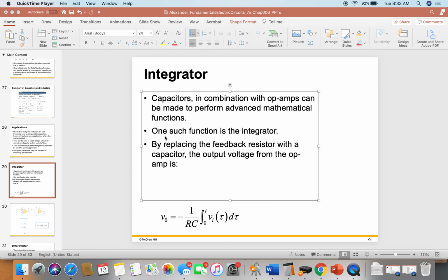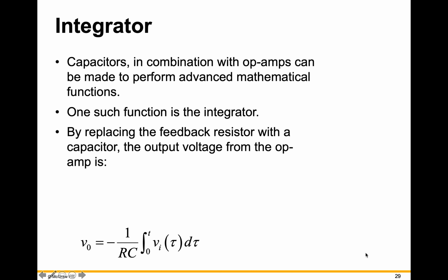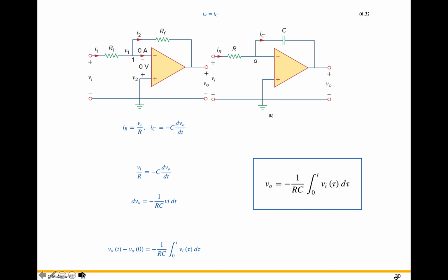There are a couple of applications for inductors and capacitors that make for some useful and kind of different circuits. The first one that I want to discuss is the integrator circuit. We mentioned this in the chapter on op amps, but it's possible in the op amp to use a capacitor in order to form some mathematical functions, and one function is the integrator. So let's look at the circuit before we talk about the equation.